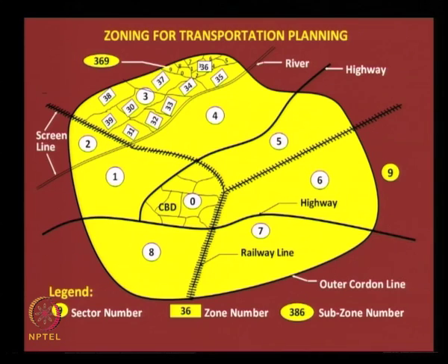And what is meant earlier is this: for example, zone 39 has its boundary as the railway track also. Part of the boundary for 39 is the screen line itself, right. So the screen line has to be taken as boundary. You should not create another boundary adjacent to the screen line. Take that itself as your zone boundary. Similarly, for zone 38, part of the boundary is the external cordon line itself. That is what is meant by compatibility with cordon lines and screen lines.